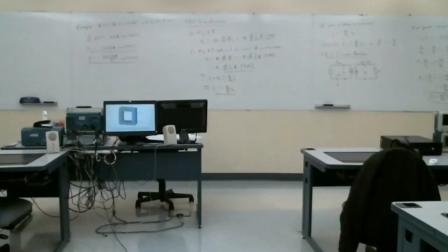But you could choose to do it differently. If you reverse I2, you need to throw a minus sign in there. From these two formulas, you can get all those other relationships for I1 and I2, or Z1 related to the load impedance. They all follow immediately from these.